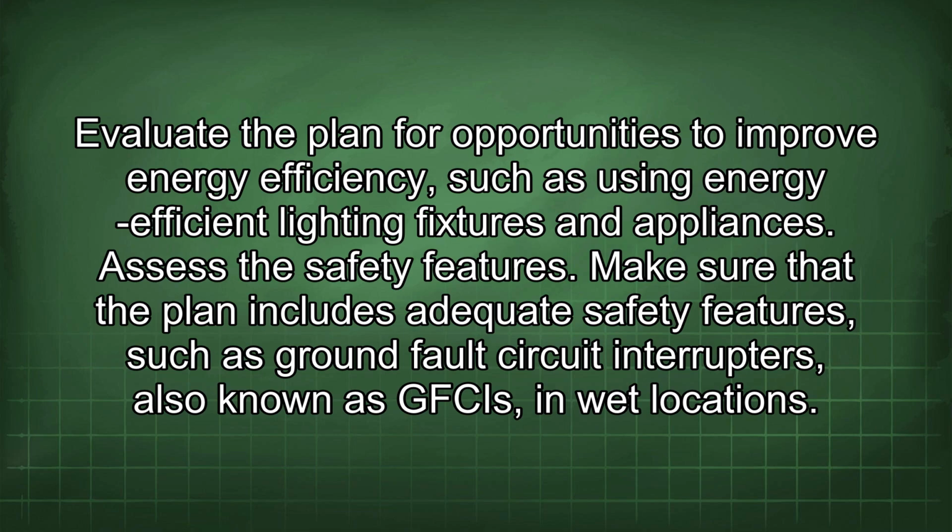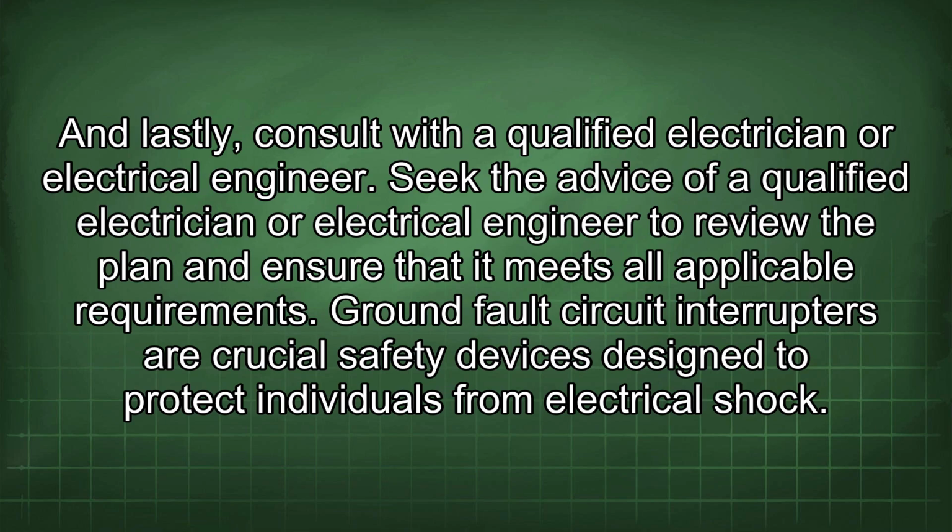Make sure that the plan includes adequate safety features, such as ground fault circuit interrupters, also known as GFCIs, in wet locations. And lastly, consult with a qualified electrician or electrical engineer. Seek the advice of a qualified electrician or electrical engineer to review the plan and ensure that it meets all applicable requirements.